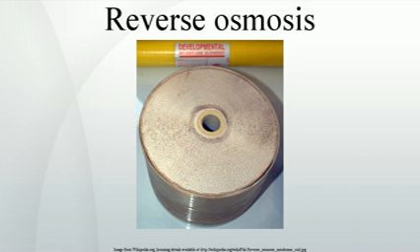This process requires that a high pressure be exerted on the high concentration side of the membrane, usually 2 to 17 bar, 30 to 250 psi, for fresh and brackish water, and 40 to 82 bar, 600 to 1200 psi, for seawater, which has around 27 bar, 390 psi, natural osmotic pressure that must be overcome.